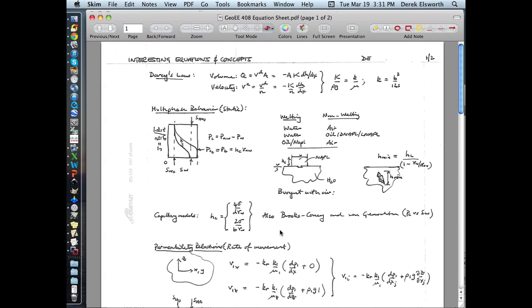So you know Darcy's law. We've written it a variety of different ways. So volumetric flow rate, Darcy velocity times area. Certainly the assignments that you've done, you've been able to do them by writing it in this way, where you can define permeability as some kind of hydraulic conductivity, as some kind of equivalent hydraulic conductivity.